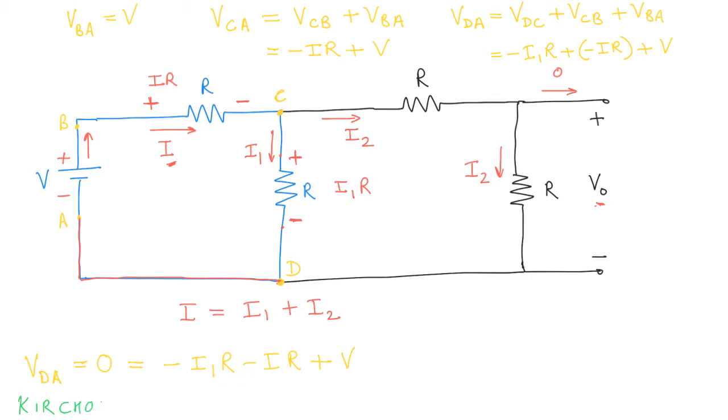It's a very famous law that we use again and again in electronics. Kirchhoff's voltage law basically states that if you add up the voltages across all the components in a particular loop, the sum is equal to 0. The basic idea is that if you go through a loop completely, you return to the same point. So when you add up all the voltages, it has to sum up to 0.